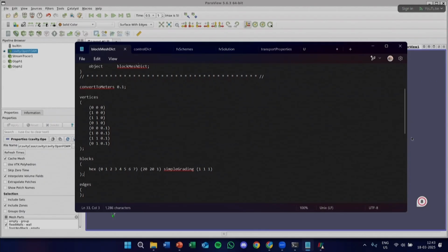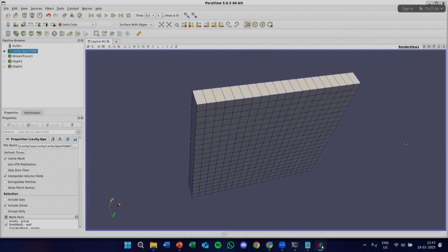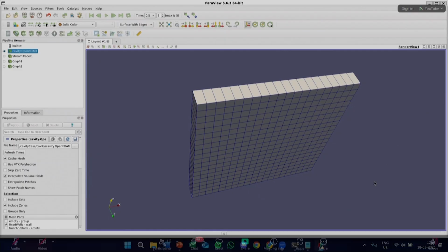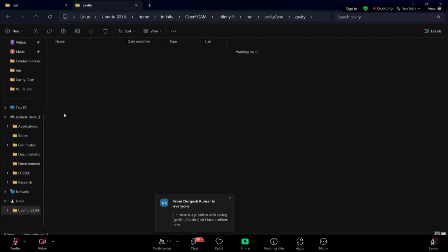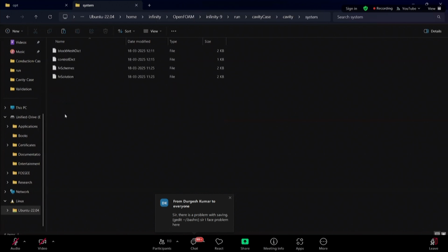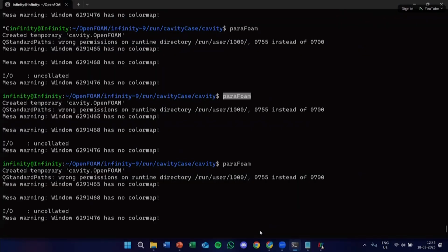Excuse me, sir. So actually, I'm running with OpenFOAM. Mine is 2024 actually. In that cavity folder, the blockMeshDict folder is there. Yes, whatever you show. I'm running with this command, blockMeshDict. No, you don't have to run blockMeshDict. You have to run blockMesh. Only blockMesh. Yes, only blockMesh.